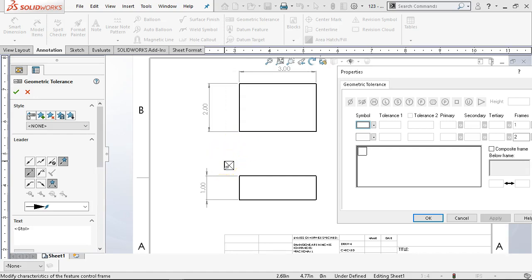So I want to look at it from the standpoint of the manufacturing side. What are probably the first geometries that I'm going to machine? But again, maybe that was the point I was going to make with the GD&T handbook: the drawing does not drive the manufacturing process. It does not suggest, it does not even say you have to do it this way.